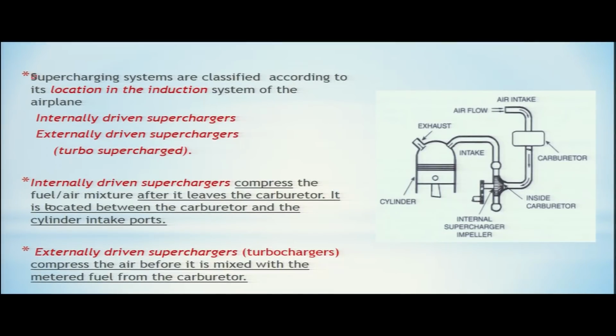One is the internally driven supercharger, another is the externally driven supercharger. Now, what are internally driven superchargers and what are externally driven superchargers? Internally driven superchargers compress the fuel air mixture after it leaves the carburetor. You can see in the diagram, this is your air intake, it is coming inside, it is flowing through the carburetor, and from the carburetor the fuel air mixture is coming.